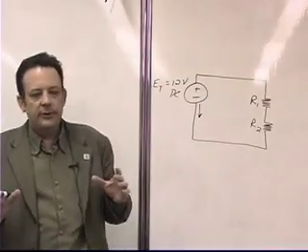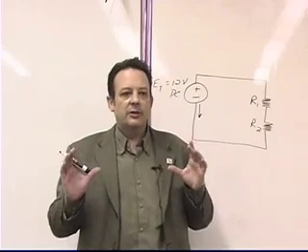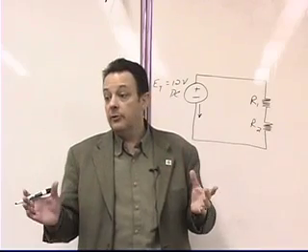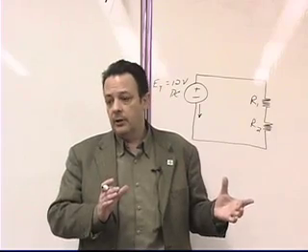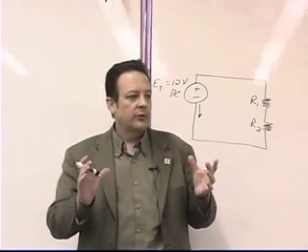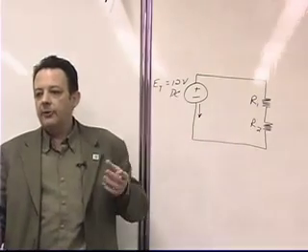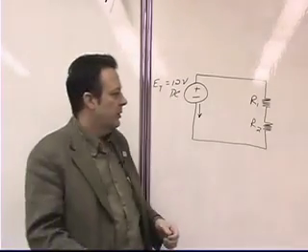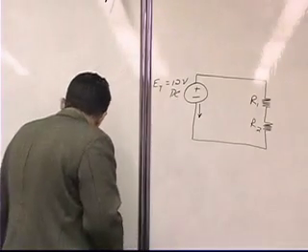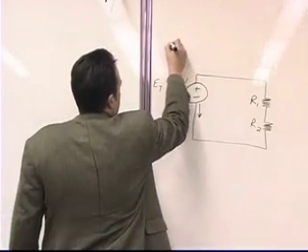But internal resistance is really what tells us what the limitation is of the device that we're using. It also tells us a lot about voltage regulation and how much the voltage is going to change on the output terminals of a battery as the load increases, or as you add additional hair dryers. So let me just first label this as what it is.